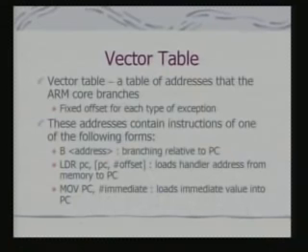But it is strictly not always that way, because the vector table, which is a table of addresses where the ARM core branches when an exception occurs, may not have space, and really does not have space, to put the complete service routine in that table itself. So, in the table you actually have a branch instruction. It can be explicitly a branch instruction, or any other instruction which modifies the PC. On execution of this instruction, the control gets switched to the interrupt handler.